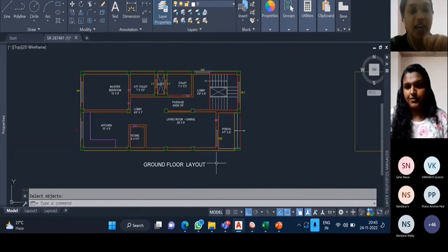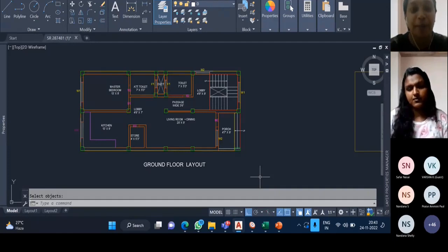The logic is that when we consider center lines, we have to remove the portion of the columns. Otherwise, the column is in RCC and the walls are in brick masonry. These are two different materials and the rate analysis will be different for them. So in order to do that deduction, we are providing the columns even in the architectural diagram. Okay, just go to the scanning part, Daniel.